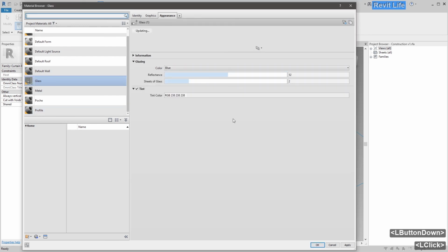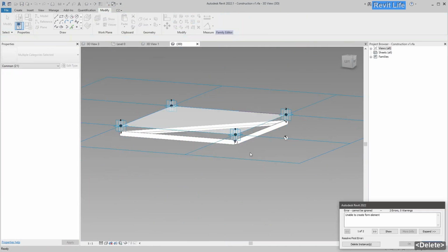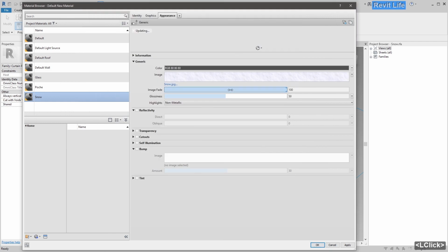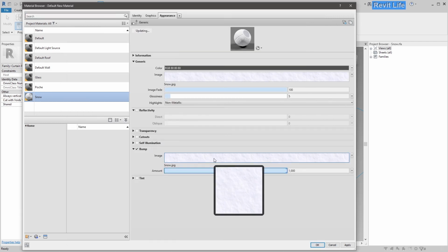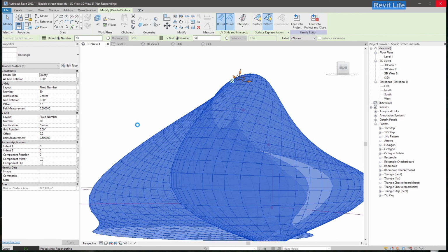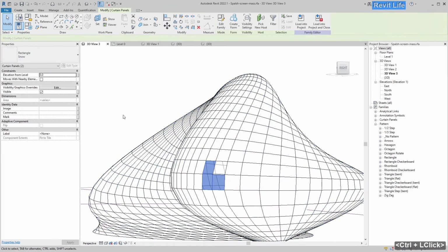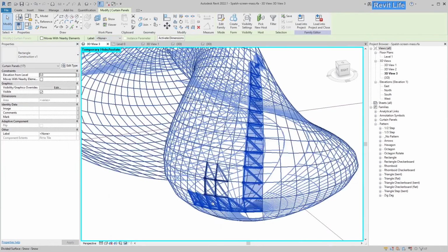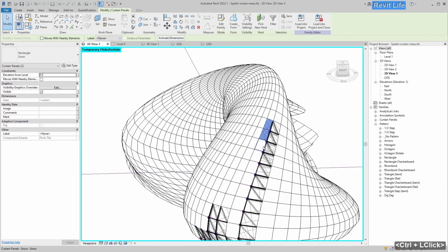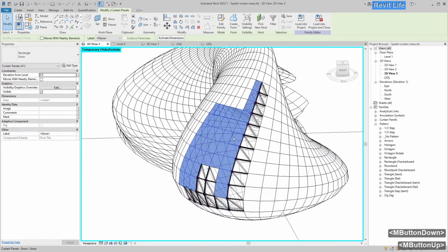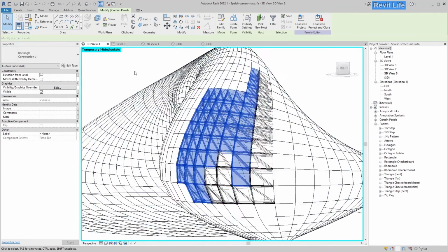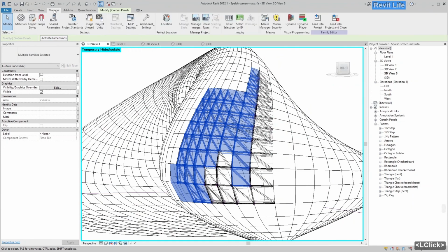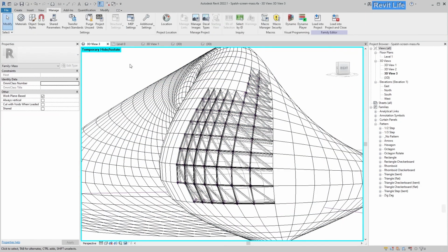And next I had an idea to make not just one family with all the visibility parameters to the pipes and to the concrete, but to make multiple families, because when Revit has to populate the surface, divided surface, with this one family that has all the information about the pipes, it has to calculate all the locations, all the possible locations for the pipes. So when I create multiple families with one family that has only just the plane for the concrete, it has to calculate only 4 points and the surface between those 4 points, and it's much faster. So that's what I did.